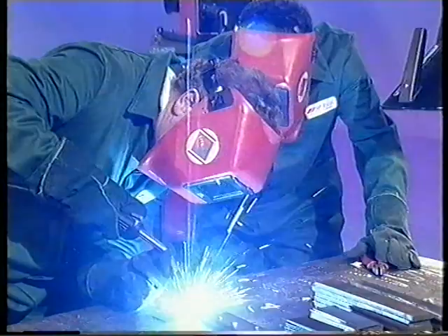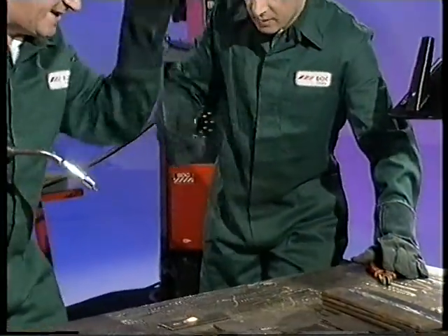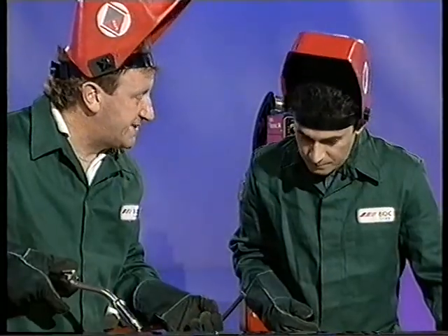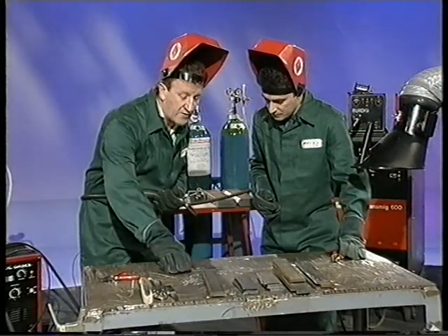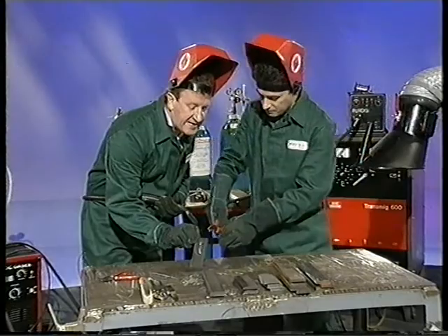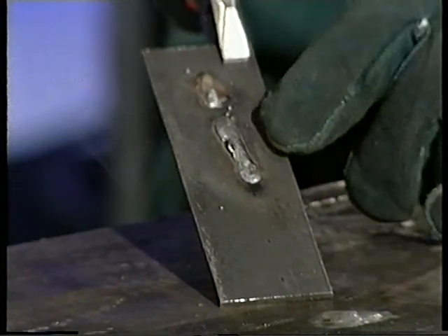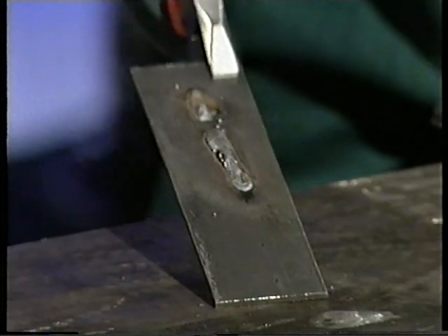It's altogether more energetic. Lots of spatter, fairly straight bead as well. Now that's certainly dip welding, the short circuit's taking place, but now there is too much wire for the amount of voltage that we have. And you can see on the weld bead itself, it's quite peaky, and as you commented, there was quite a bit of spatter there as well. Yeah, so there's basically too much wire going into the weld pool.